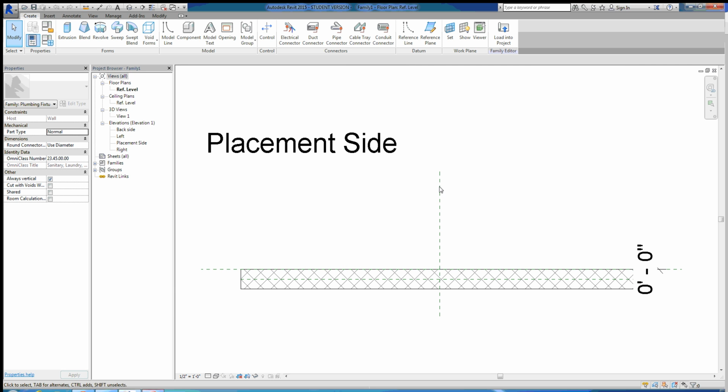When we're creating our water fountain, the main thing we want to worry about is creating these reference planes to draw our water fountain on. If you remember from class, making a reference plane makes it so that we can parameterize the dimensions between the reference planes and then lock our object to those reference planes. So if those dimensions change, the reference planes will change, and then the locked objects that were attached to those reference planes will change as well.